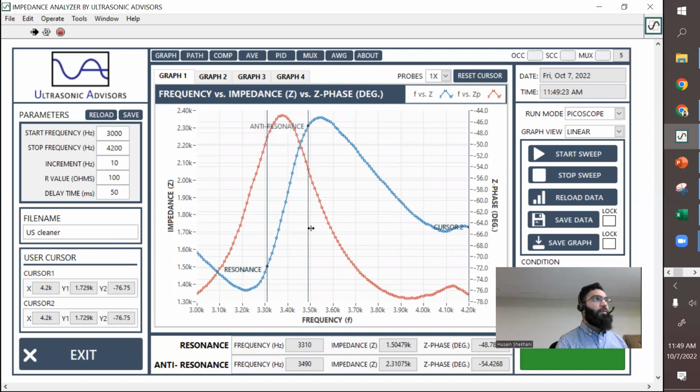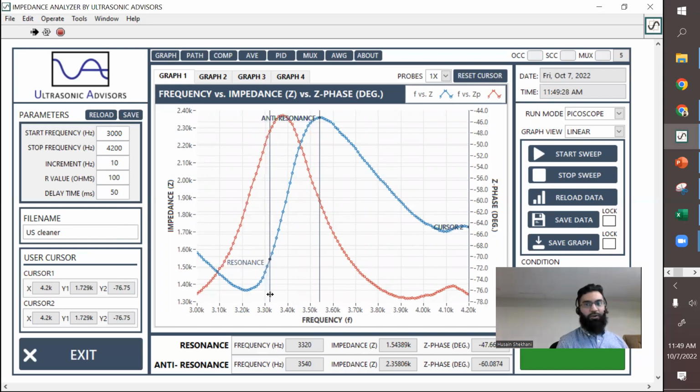You'd be calculating a higher coupling factor, and you'd have your coupling factor actually affected by the quality factor. It would be an incorrect measurement because of that, and you would have the wrong coupling factors calculated. Especially in FEA, when you're trying to correlate your mechanical and your electrical data, and you're trying to make sense of what to input for parameters, you have to be measuring things correctly. And I think I'll end with that.